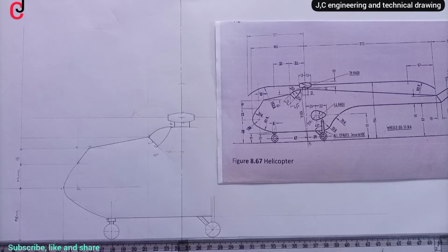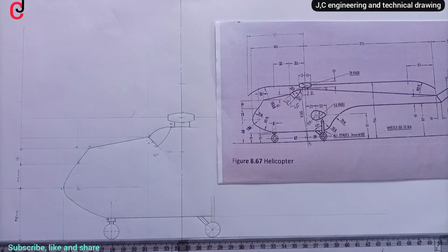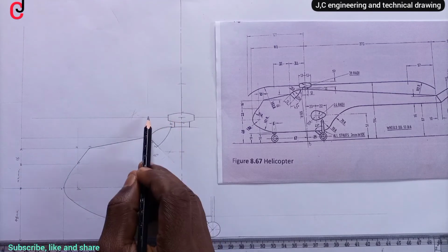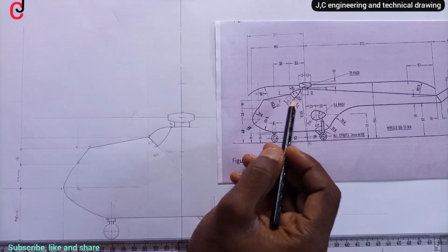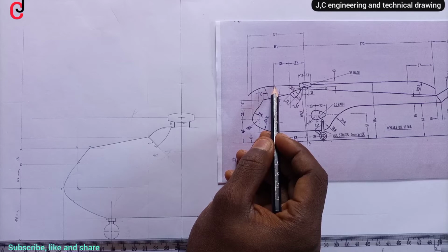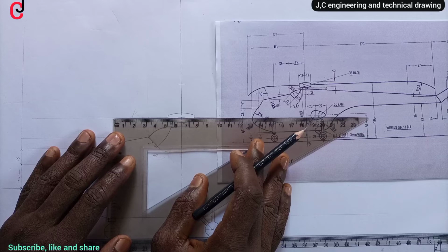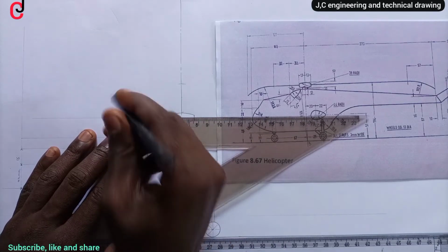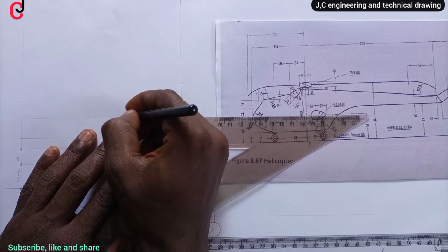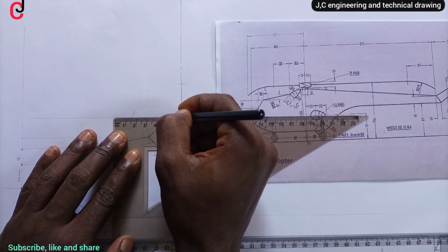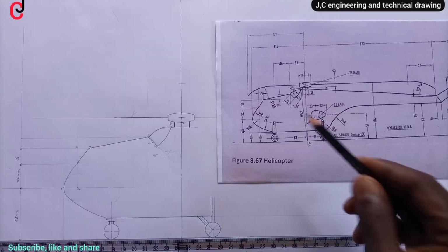And then from our diagram, you can see from this midpoint to this portion here is 32 millimeter, from this midpoint to here is 32 millimeter. Now also from this point towards this point here is 32 millimeter, so we'll measure 32 millimeter. Then we'll indicate the point and then we'll outline all through, and then you can see a curve here